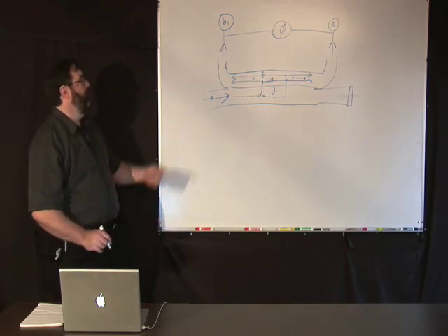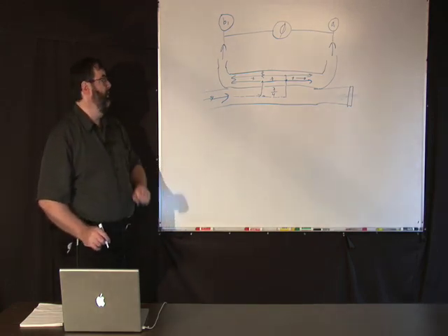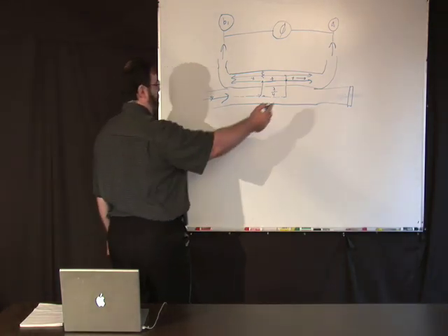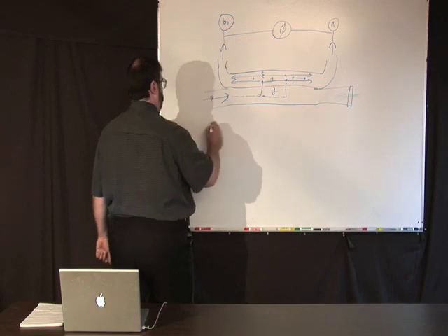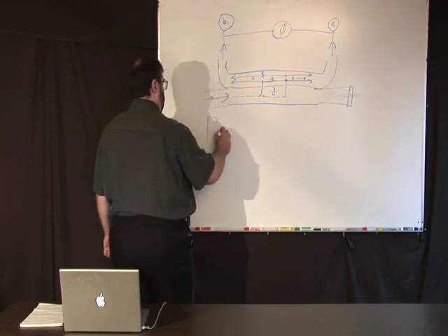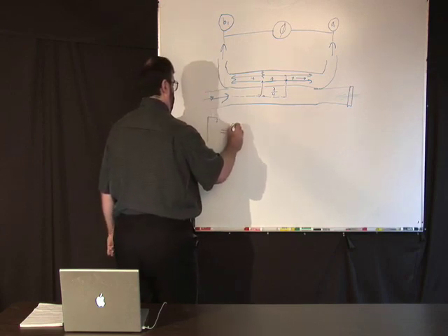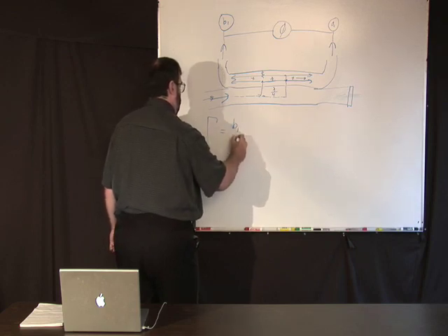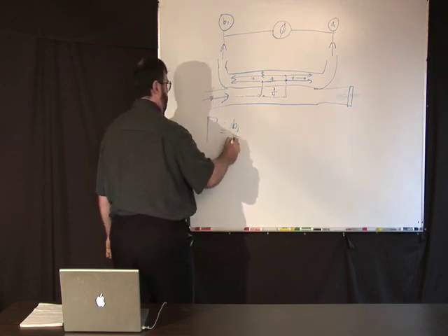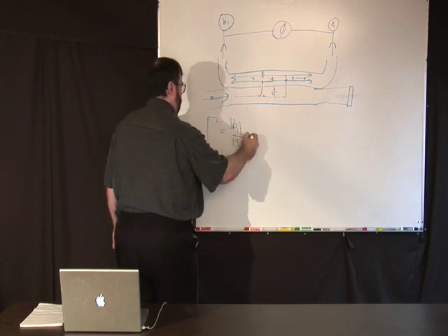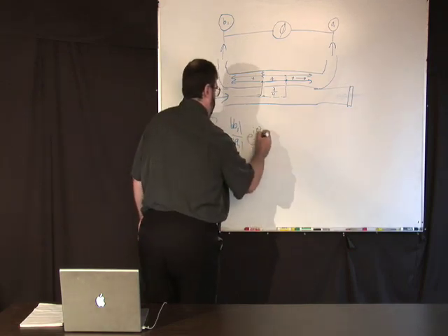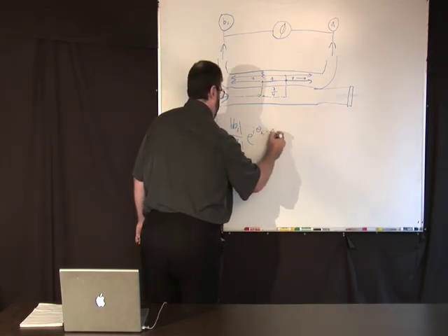Okay, so we have this thing where we can measure A1 and B1. Well, we know that if you stick some load out there with some reflection coefficient gamma, that's going to equal B1 over A1, let's say these are magnitudes, times e to the i theta B1 minus theta A1.